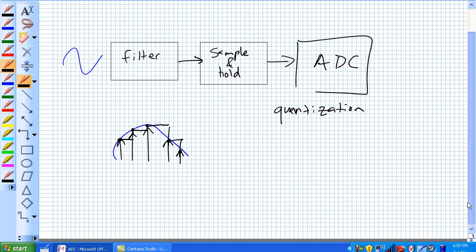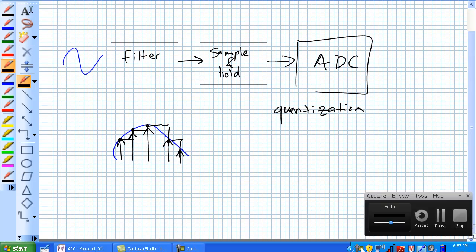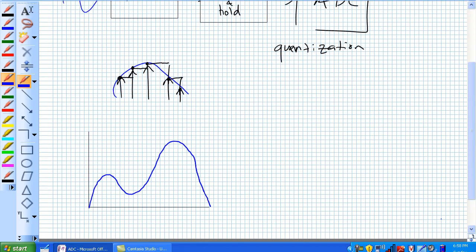Okay, say we have a wave that looks like this guy right here, and we are going to sample it using a 2-bit code. Our 2-bit code can obviously take on values of 00, 01, 10, and 11. This is our analog signal that we're going to try to stuff into these 4 categories.